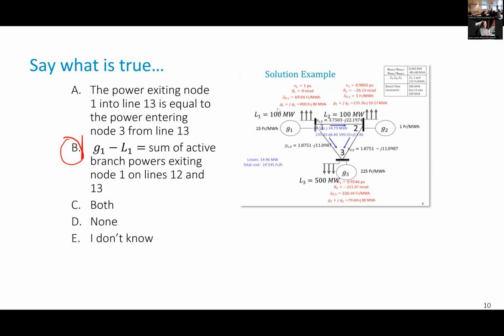In a system like this, we might want to say L1 is consuming 100 megawatt, so they will need to pay for 100 megawatt. L2 will pay also for 100, L3 will pay for 500, but who will pay for the losses? The total consumption of the system is larger than 700, because it's 700 plus the losses. Who will pay for the losses? That's the problem of attribution of the losses. It's a very difficult one. It's done only approximately. Since the losses are small, that is okay, but there is no non-ambiguous, universal way of saying who caused which loss here. The losses are the result of the global system operation. So they have to be paid by everyone, typically proportional to what they use here, or using other mechanisms that would require more discussion.